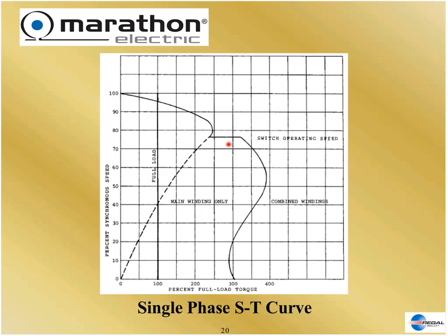This switch point is what happens when you turn the car key on to start the engine and then you let it go. It goes back to its normal position. The start motor is disengaged from the system. That's what this switch point is. And it uses a device like this, if I can show it to you. It's called a centrifugal actuator that rides on the shaft. Now, there are more mating parts to this, but this is the secret of this switching point.